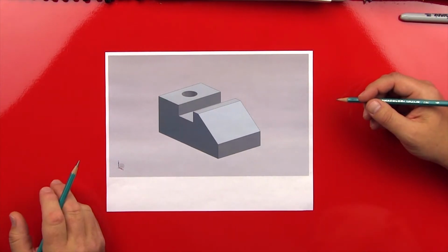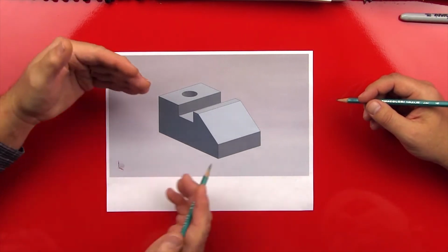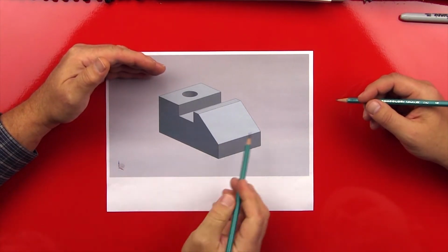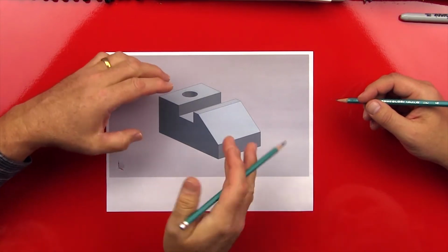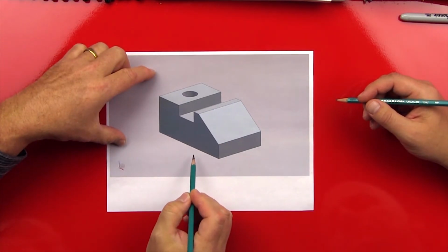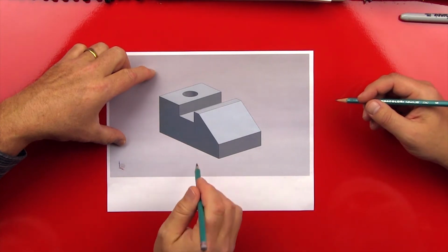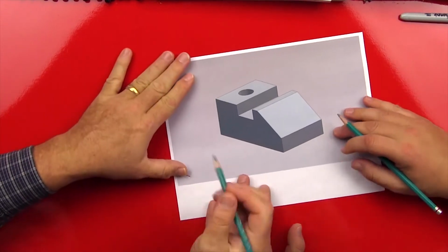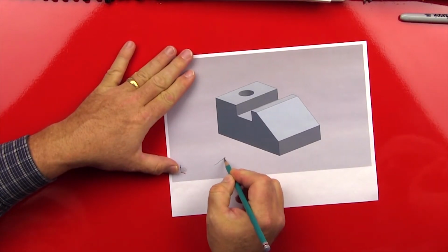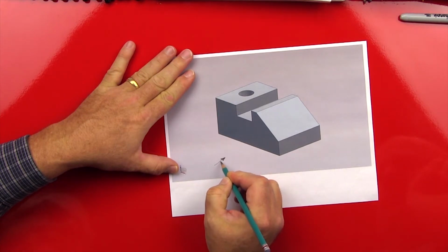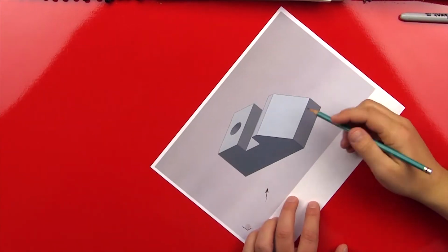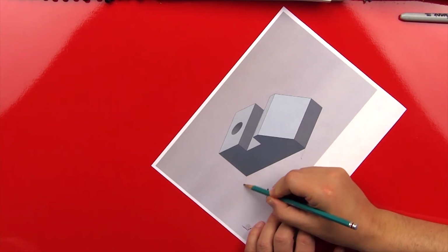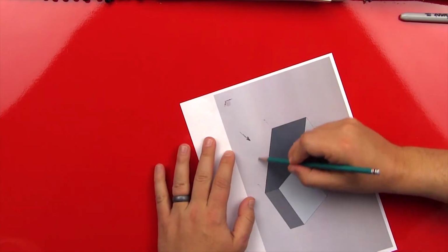One of the ways to do that is to draw sketch planes, and then project lines that come off of that onto this front plane as dots. And then connect the dots. And so I'm going to let you sketch a front view. So let's assume that we're going to use that direction as our front view and sketch a plane that we can project onto. So it's going to float out some distance in front of that.